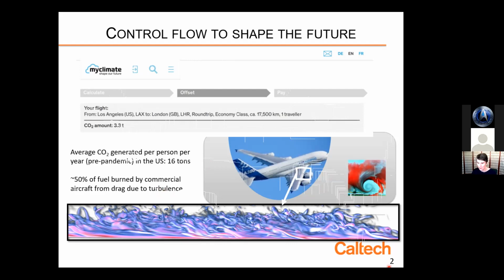Now, what's going on if we look at this? Goodness, I can see this laser pointer is doing something funny to my screen. I'll take that off. If we look on the wing, say, or even on the fuselage of a commercial aircraft, and we look very close to the surface, in the boundary layer between where the flow travels with the velocity of the aircraft and where it adjusts to the velocity of the quiescent air around, or the wind speed around the aircraft, there's a lot of activity. And so for aircraft of this scale, the boundary layer is turbulent for a good portion of wing and fuselage. And we'll spend a little more time with some of the details that you can see down here in this bottom panel. That's a representation from a turbulence simulation, just showing some of the turbulent structure or coherent vorticity that you see in a turbulent boundary layer.